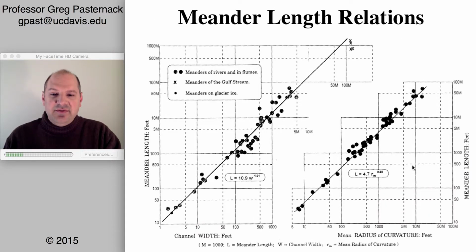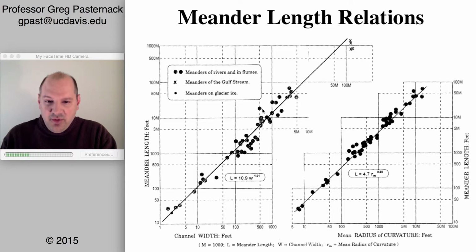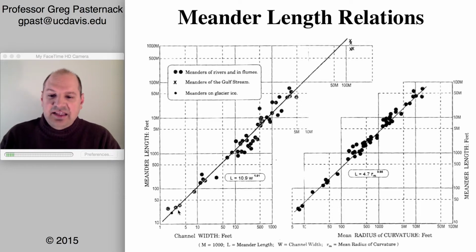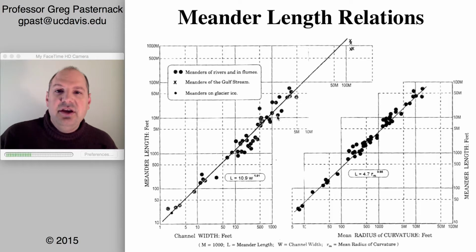Of course, if you look at these functions and say that I was restoring the river and it was right where this dot is, you're designing something to the line. So if there are some local factors that would drive it to actually have a longer length, that wouldn't be captured by this. But the idea here is you're using this data to get the central tendency, and you're assuming that discharge is not only the primary control, but it is the control, and that other things will matter so little that it won't affect the consequences of how that stream functions.